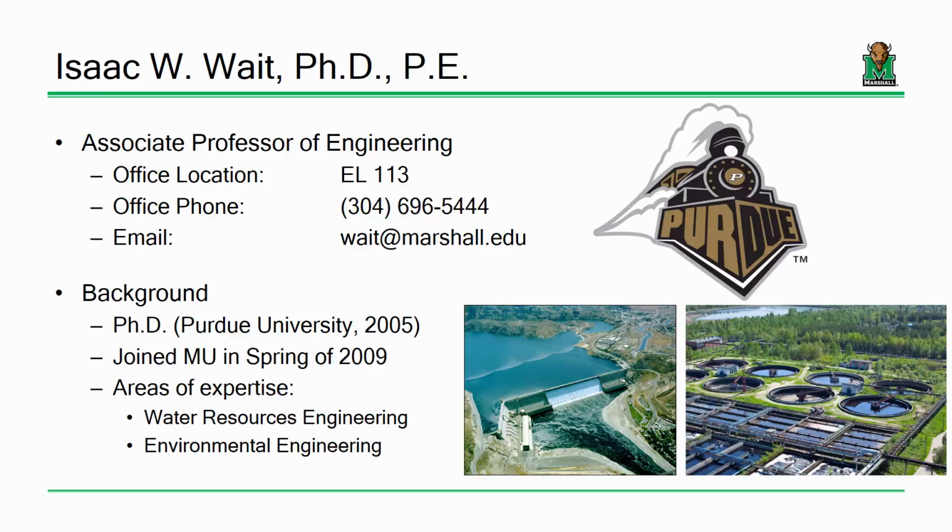Actually, water treatment and wastewater treatment have a lot of parallels, whether you're purifying river water so that people can drink it, or purifying sewage so that you can put it back out into the river. You have to settle solids out of solution, and that's what a clarifier does. These other rectangular pools may be chlorine contact basins in the case of a drinking water treatment plant, where you're trying to kill any pathogens that are in the water. And we can tell that this is actually a wastewater treatment plant because there's a lot of air being added to these pools, and that's for activated sludge.